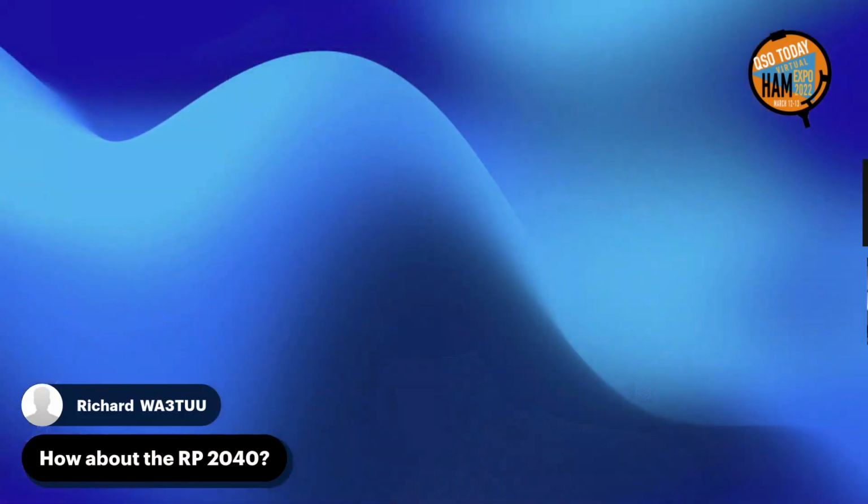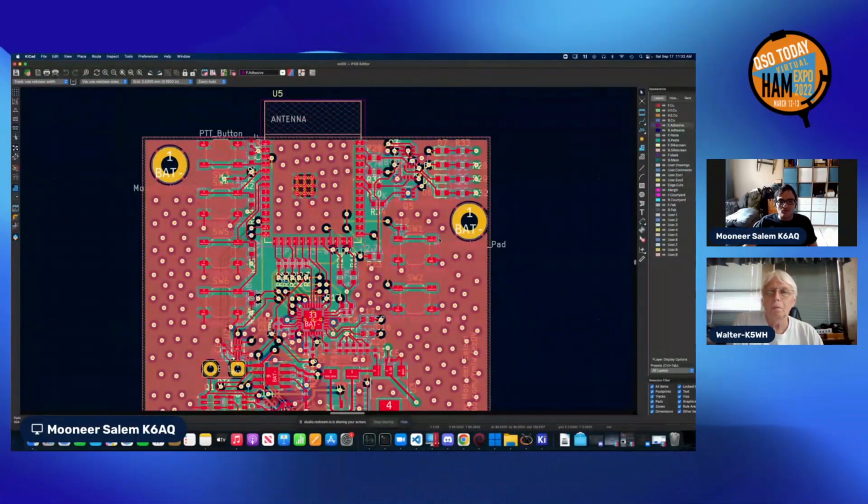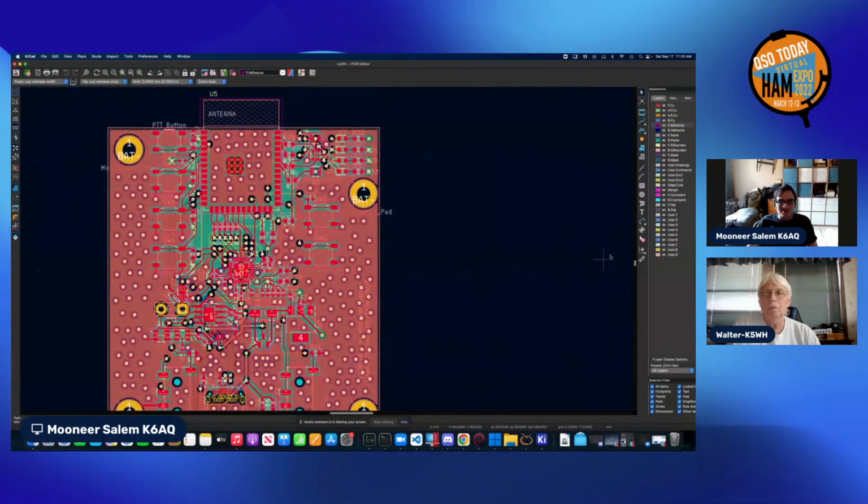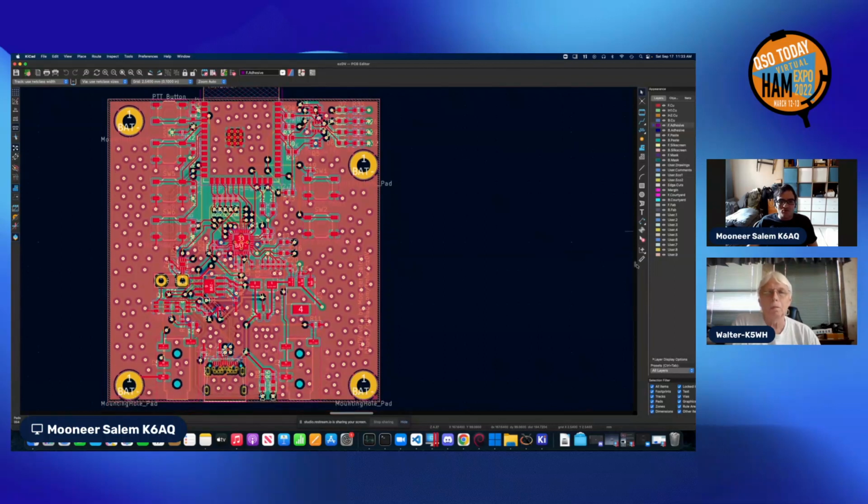There is a share screen thing. I have the current schematic, or I guess the current PCB, up. This is the 0.3 board that I just had made. The buttons on the left-hand side are PTT, mode, volume up, and volume down. And these two buttons are designed for resetting the ESP32 as well as putting it into DFU or flash mode, so you can flash new firmware.